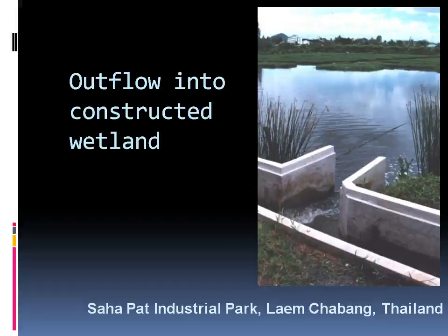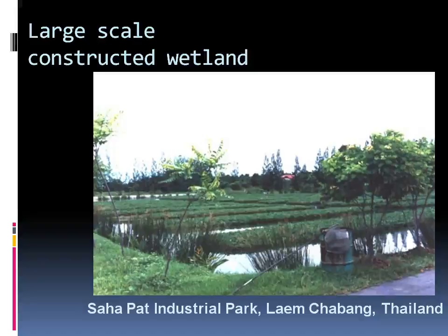Thereafter reverse osmosis, where the water is passed through a membrane impermeable to dissolved ions. Then the biological method, where algae and water hyacinths grown in ponds can be used to consume nitrates and phosphates. The dissolved organic material can be directly removed from the water by certain aquatic plants such as duckweeds.